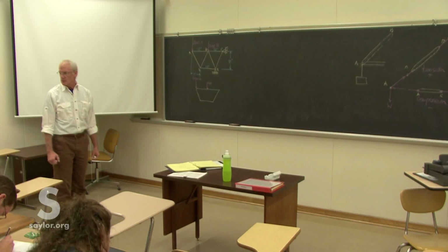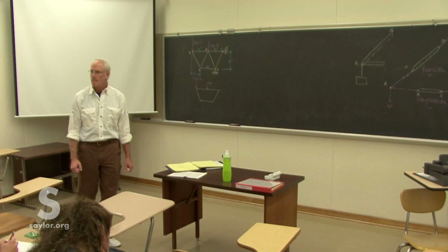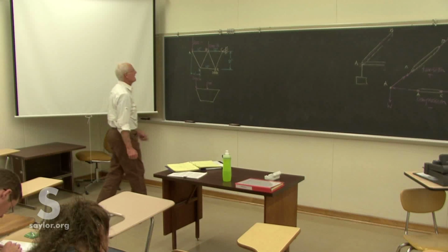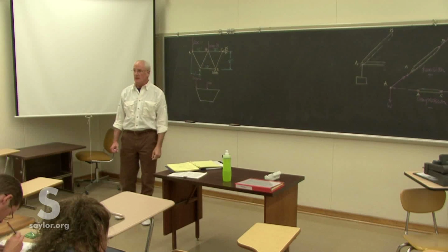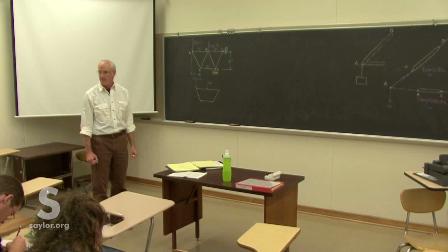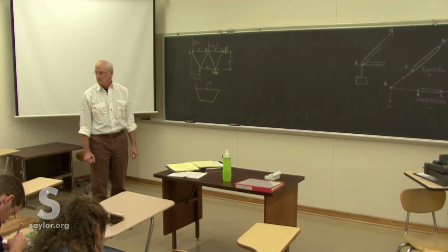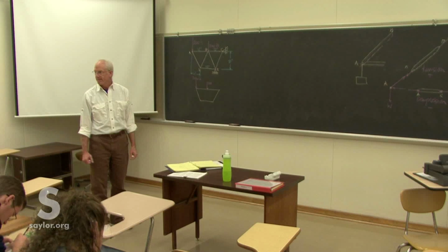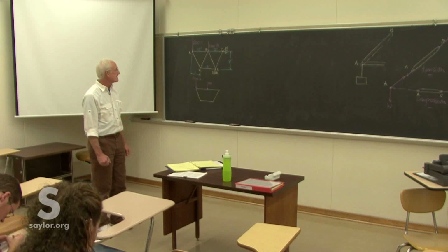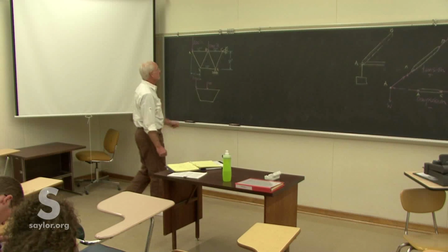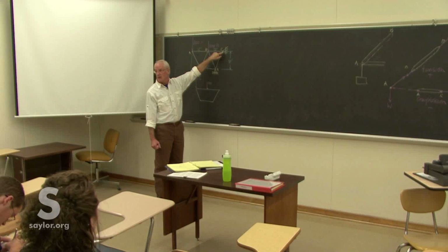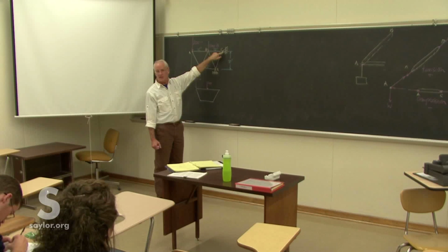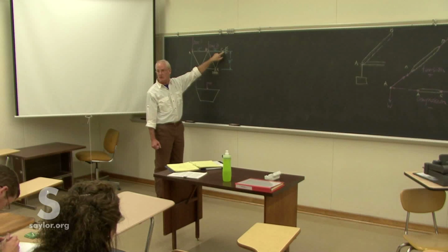So what are the reaction forces on this? Some reaction force at C and some reaction force at E. But what? This is a pin supported joint up here. And so what are the type of forces that a pin support can exert?